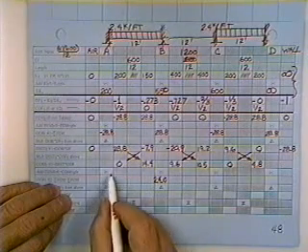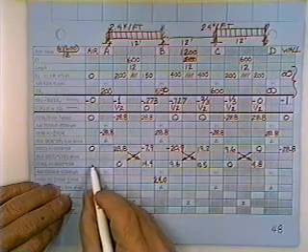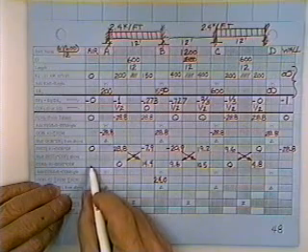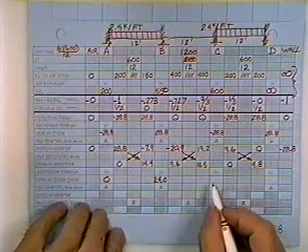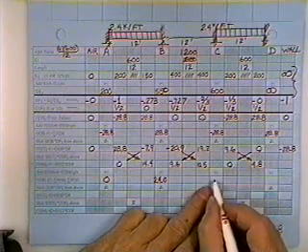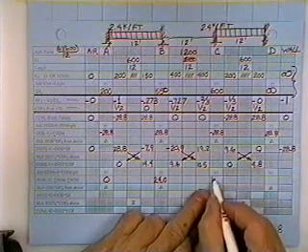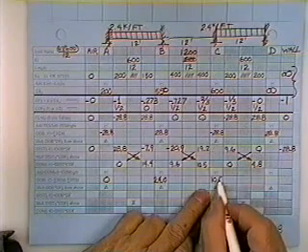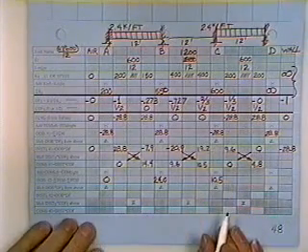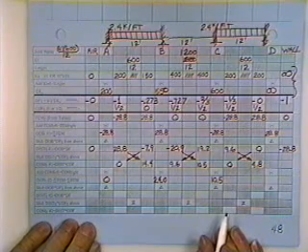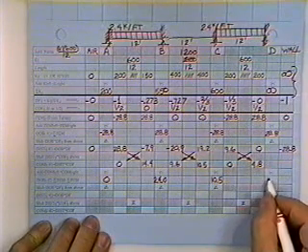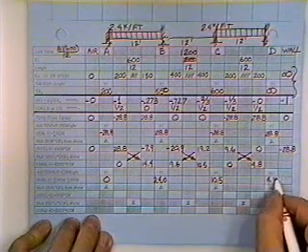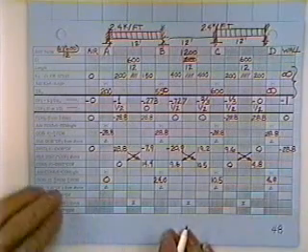Joint A is kind of nice. You add the moment to the left, you add the moment to the right. There wasn't even a place at the left. There isn't any. He doesn't have any torque in his wrench. The guy standing at joint B says, well, things are better than they used to be, but I still got some torque in my wrench. I say, how much? He says, 10.5. I talk to the guy at joint D. I say, have you got any torque? He says, yep, 4.8. You merely add them up.